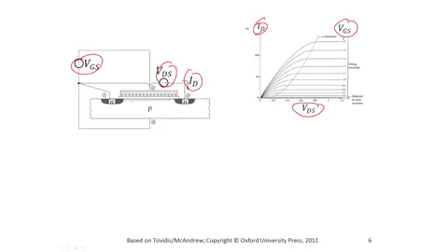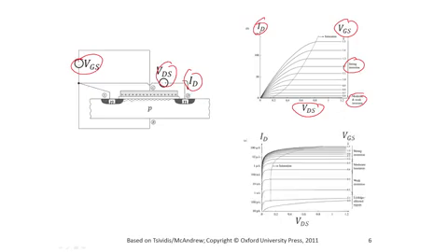So you go from one curve to one above it, and so on. It turns out, for a typical set of parameters for an MOS transistor, that practically all of this region is strong inversion, and you do have moderate and weak inversion, which is compressed near the bottom, and you cannot really see it. So instead of plotting on a linear scale, I will plot the drain current on a logarithmic scale,